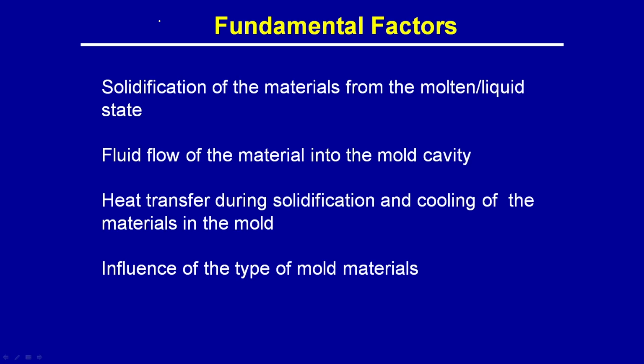So, we have been talking about processing of materials, and we started discussing solidification processing. How can you shape or get components from the liquid state? And this is the last slide I showed you. You can see here the fundamental factors. We talked about factors like fluid flow and heat transfer, which are critical factors for determining solidification processing.